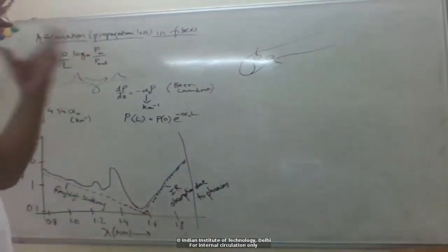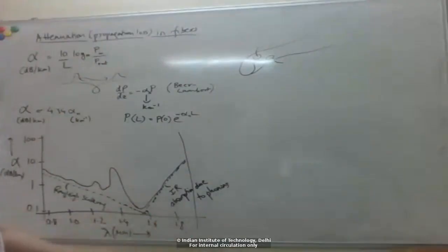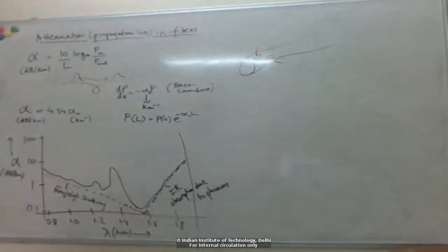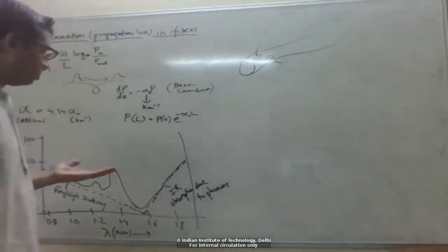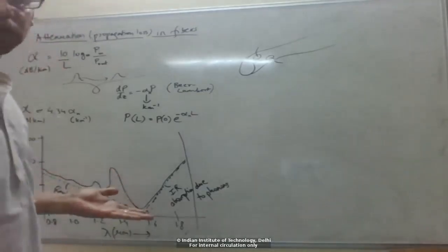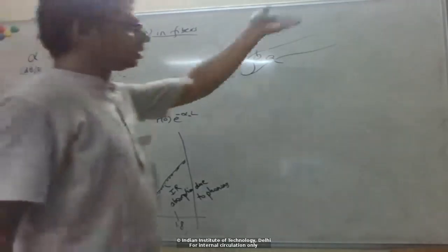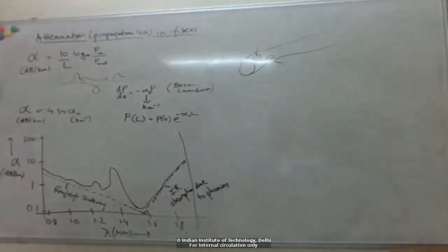So you can imagine, for example, the refractive index depends on the density, right? So there are very small refractive index variations, right? These variations are extremely small, like let's say part per million or part per billion, but basically they do cause some small amount of scattering, right? And if you have very long lengths, as we have for optical fibers, these can actually become significant, right?